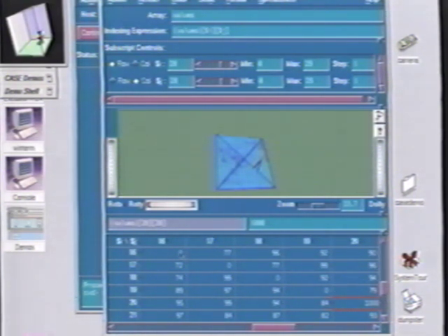Also, if I go in and look at the pattern of the array, I can see that I have a number of zeros following through here, and that this array value probably should be set to 0. So I have definitely an error that's happening there. So I can go in, modify that array value to 0, and as I've made that modification, I can now look at this and see that the spike has indeed cleared.